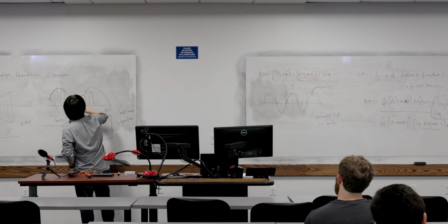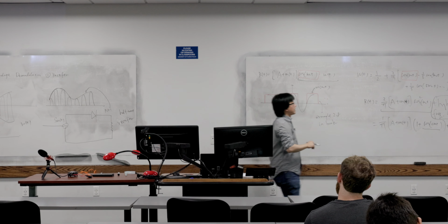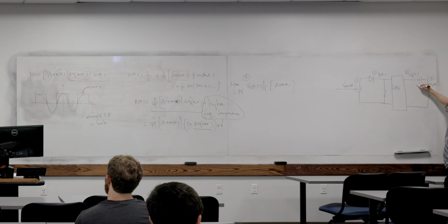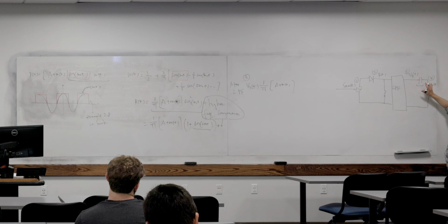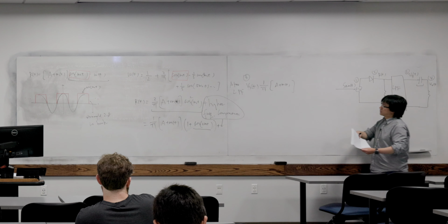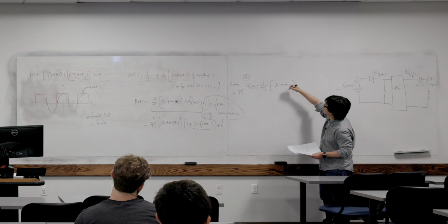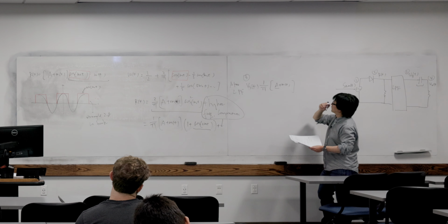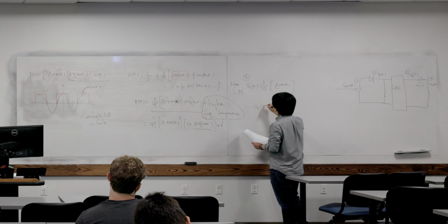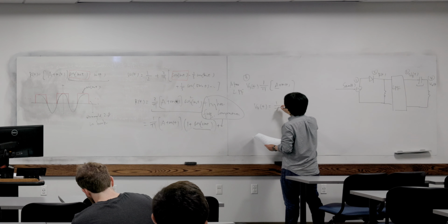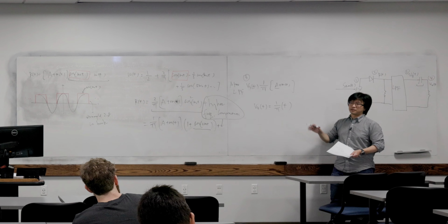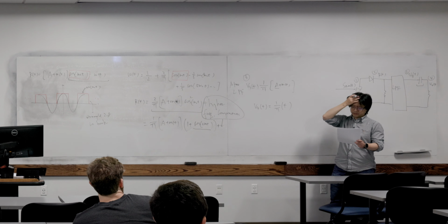And then the last step is nothing but, we use the capacitor here. The reason we use the capacitor here is to get rid of this DC component. So after that, our V4 of t would be equal to this guy. Okay, that is basically how we do that in practice.